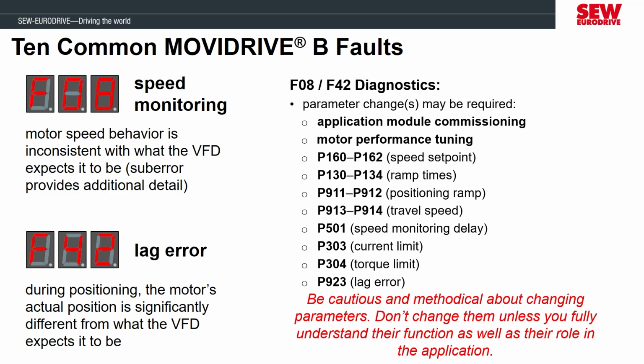When you do modify the parameters, you need to keep a record of what you change, because some changes could make the problem worse. You will want to undo the changes if the adjustments make the situation worse. I recommend to take a parameter backup right before you make any changes so you can revert back to it later if you need to.